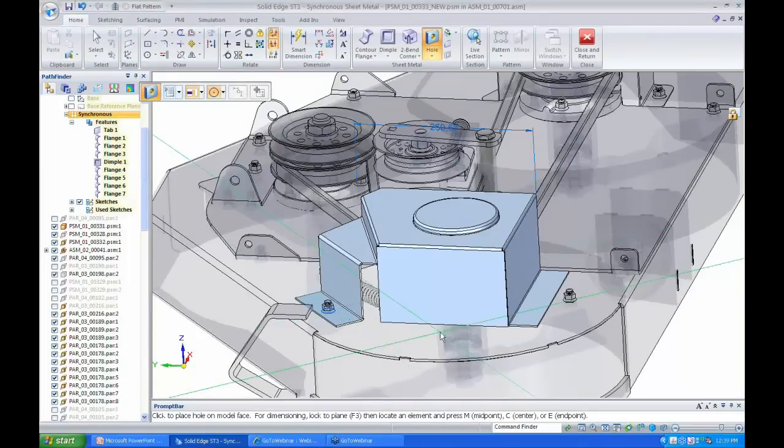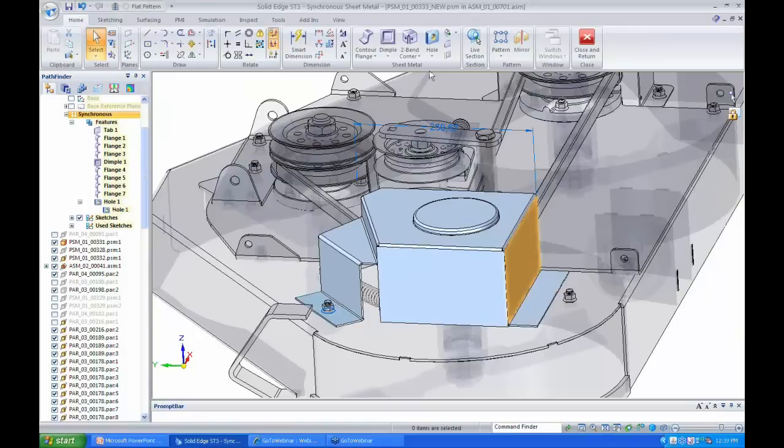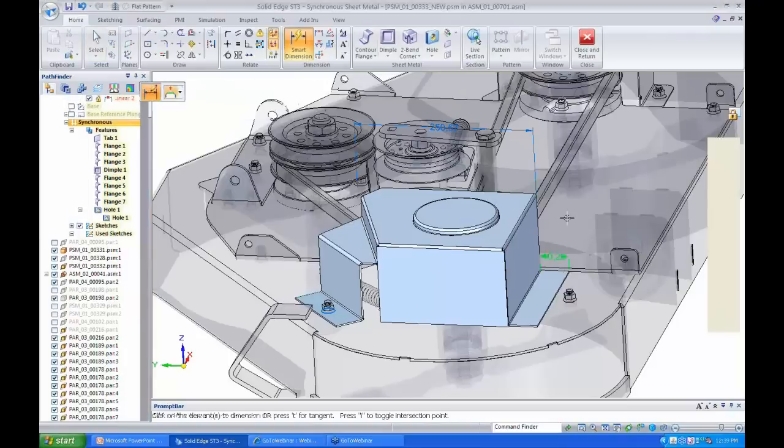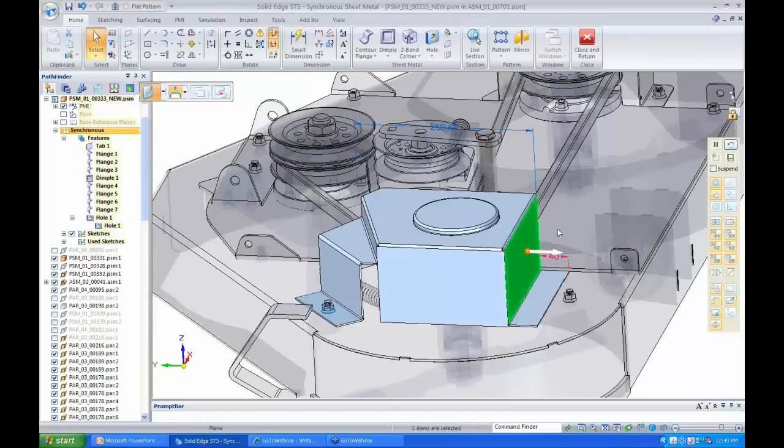All right. So on the other side, on the right hand side, I want to taper the face that is a normal face. I want to put some taper angle before I move the face to the bolted. So for that, I'm going to place a small dimension here and then give it a value. In this case, I'm going to enter 40, and then I want to lock this down. You'll see the reason why I want to lock this down, because I don't want this to change when I change the angle of this face.